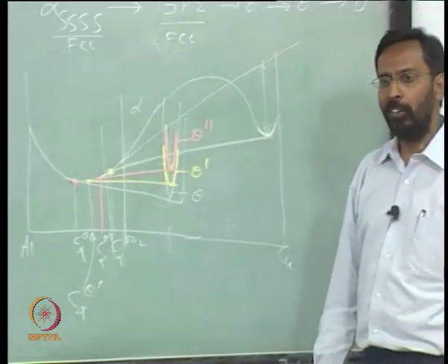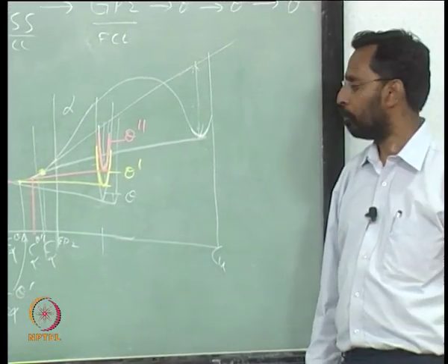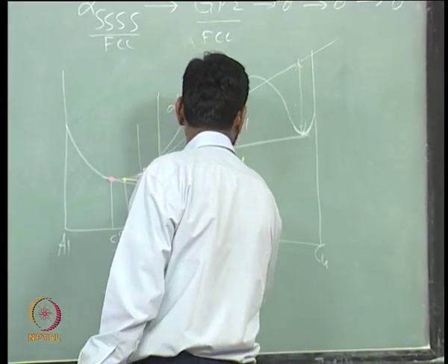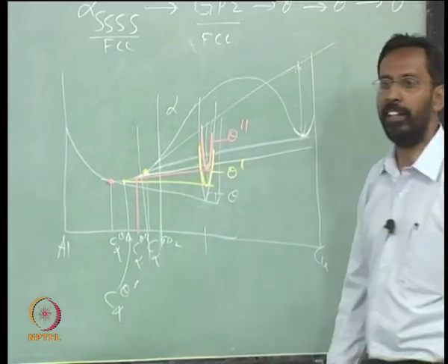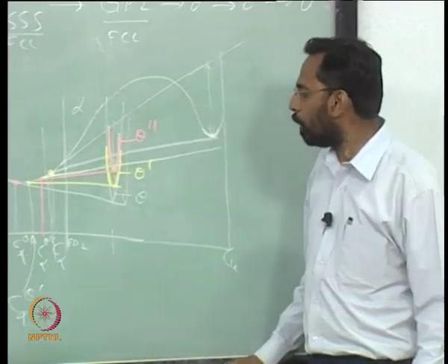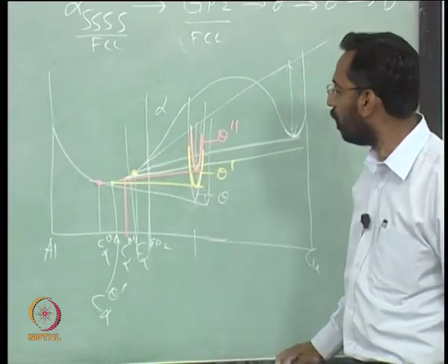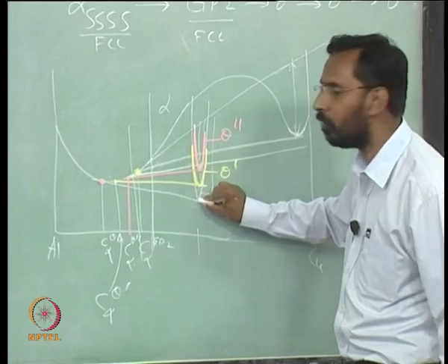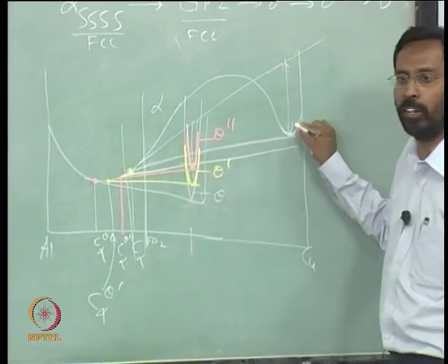But now if I choose another alloy composition, because we have raised that question, let us look at this. If I choose this particular alloy composition and draw a common tangent, I will come to a situation like this, that this particular alloy composition is such that it can have a driving force for this phase, this phase, this phase. It cannot have a driving force for this phase.